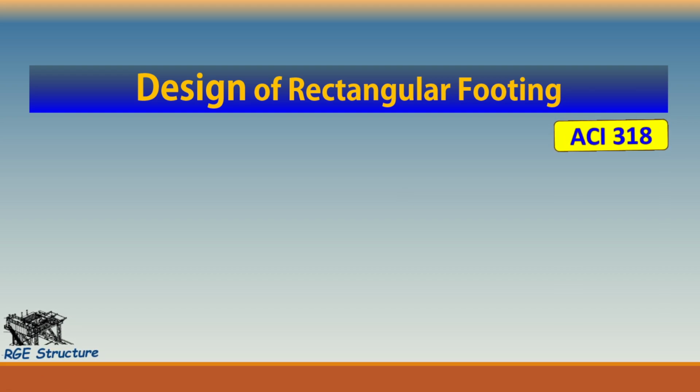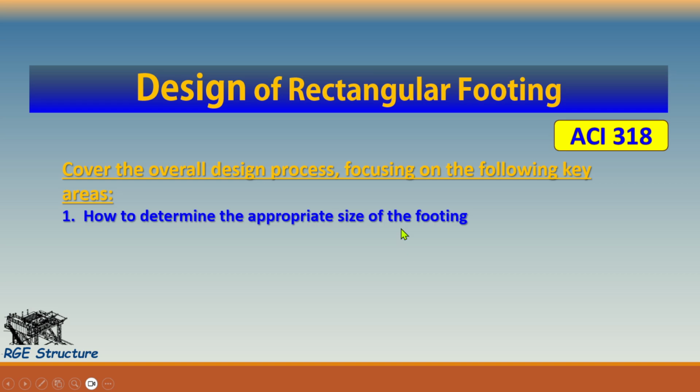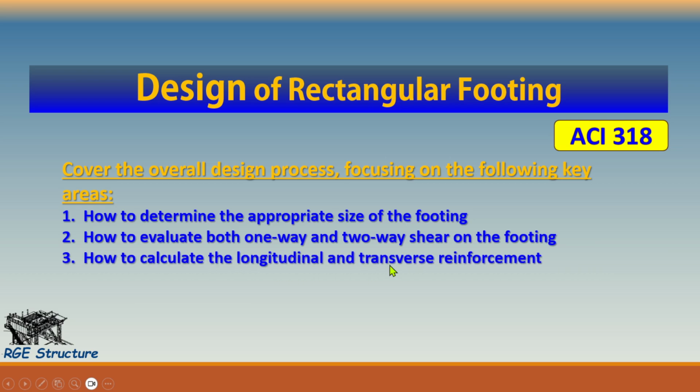In today's video, we will walk through another sample problem on how to design a rectangular footing. We will also cover the overall design process, focusing on the following key areas. Number one, how to determine the appropriate size of footing. The second is how to evaluate both one-way and two-way shear on the footing. The third one is how to calculate the longitudinal and transverse reinforcement.